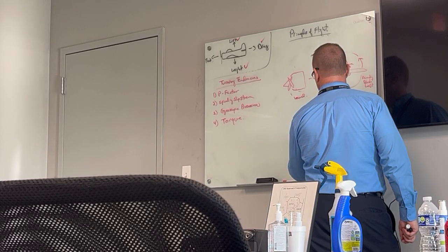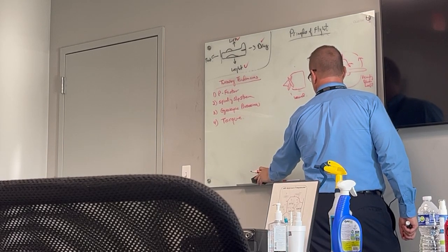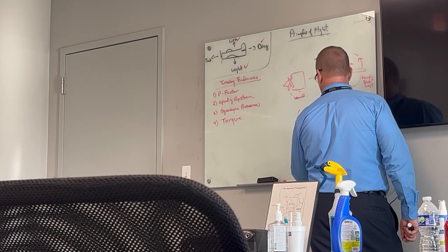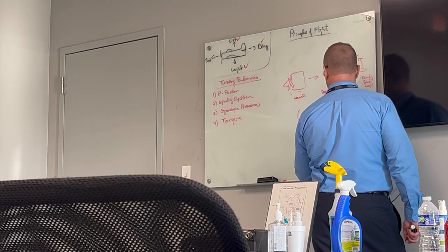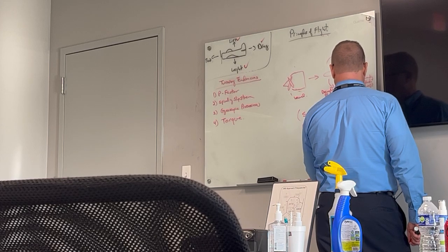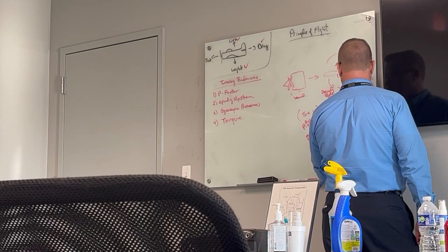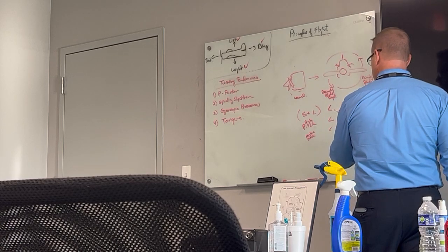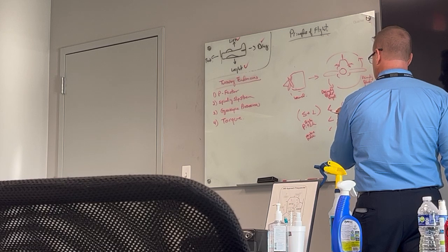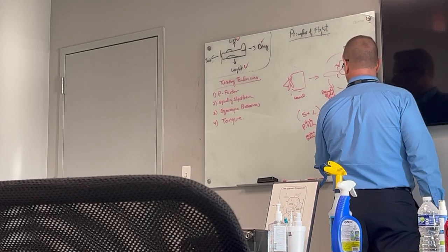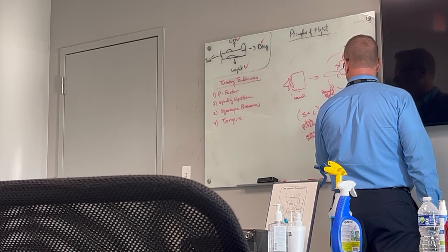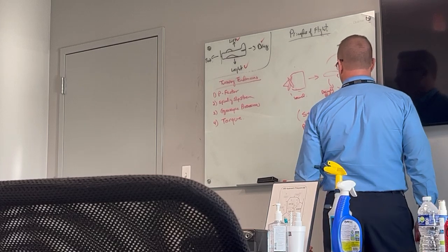If we have a negative pitch, then this angle would be greater. I drew it backwards. At a high pitch, the descending blade is going to be greater. Descending is going to be greater. With negative pitch, the ascending blade will be greater.